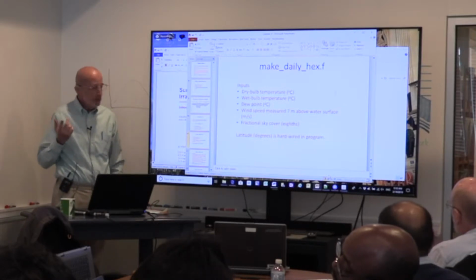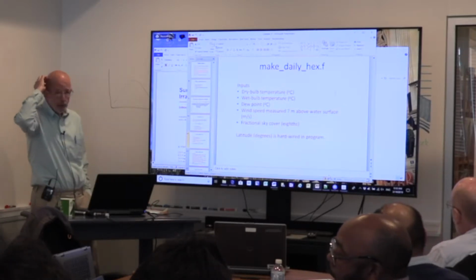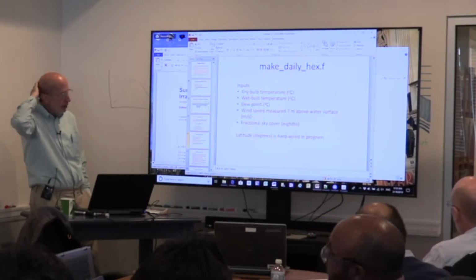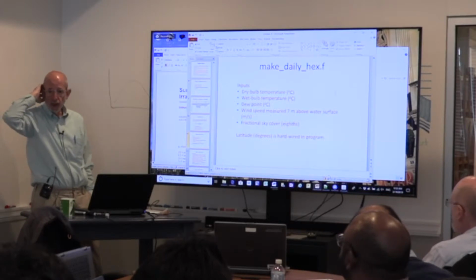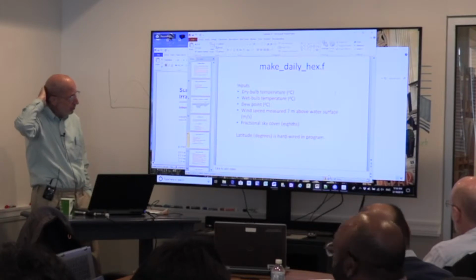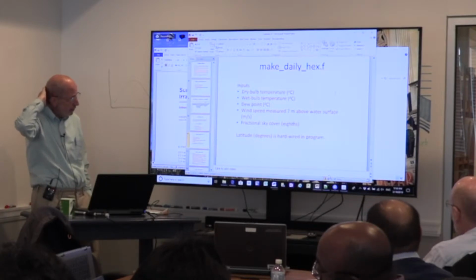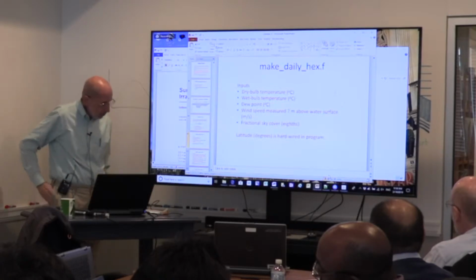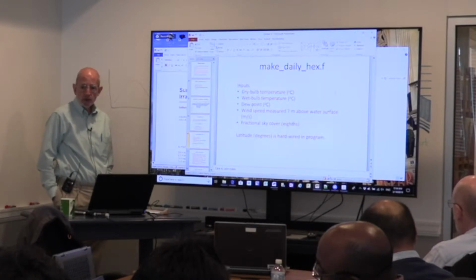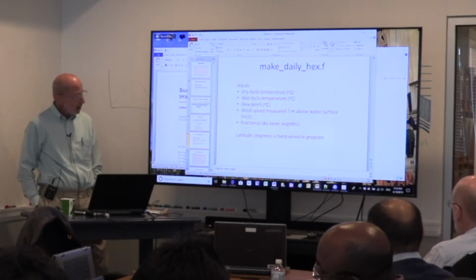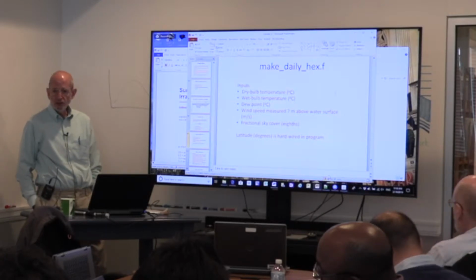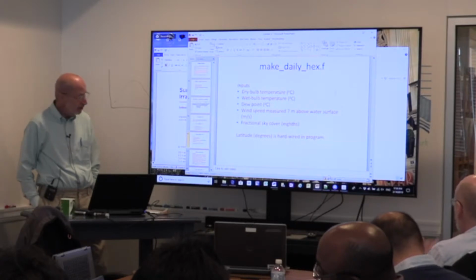So you've got a program, we'll look at it in a few moments, called Make Daily Hex Heat Exchange. It takes raw meteorological data, and it will create a water quality model MET file. Inputs: dry bulb temperature, wet bulb temperature, dew point, wind speed, fractional sky cover. It also needs latitude. At this moment, latitude is hardwired into the program for Chesapeake Bay. So if you want to apply this in, I don't know, Michigan or something, you're going to want to go into the program and make some changes. But fair enough.